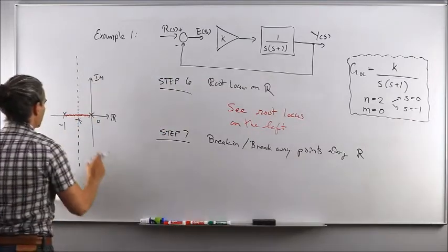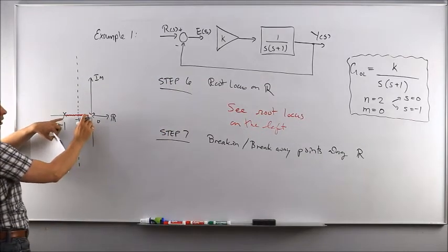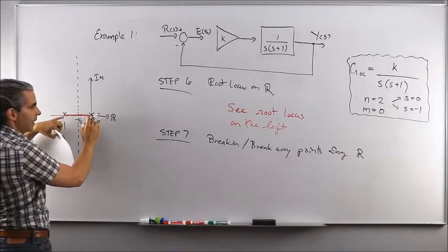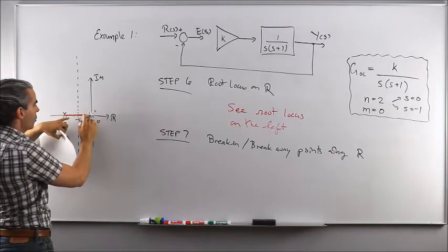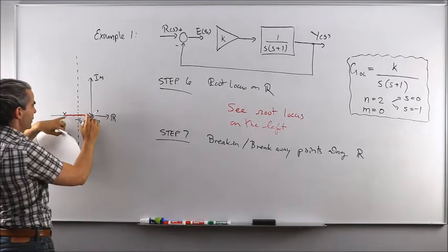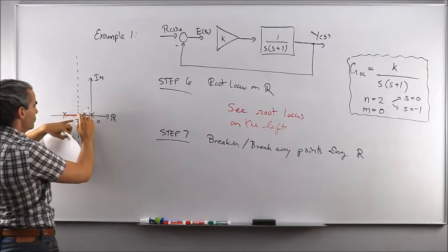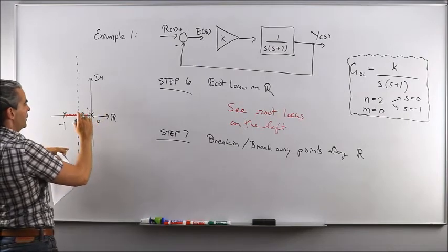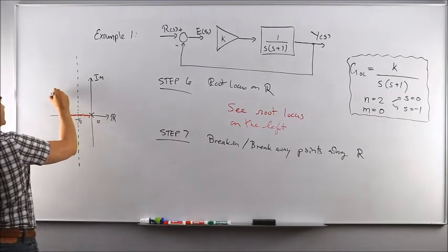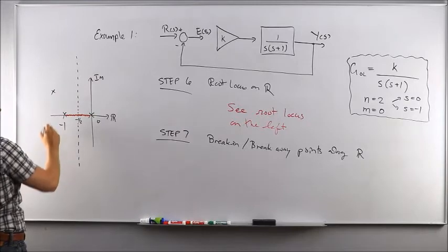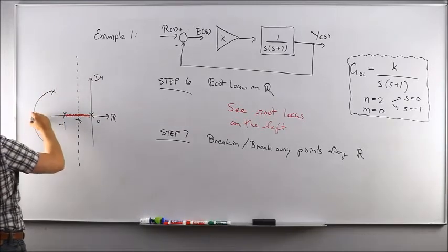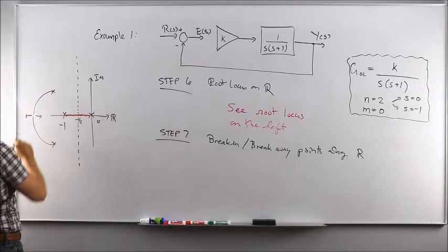Okay, because we're starting with both poles along the real axis to begin with, it means that we're going to get breakaway points because they will probably at one point move away from the real axis. All right? But if you had complex conjugate poles, maybe they would want to break in the real axis like that and do their things afterwards.